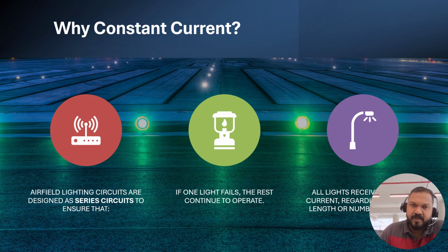From this transformer to the lights placed on the runway center line and the edge lines, similarly the taxiway center line and edge lines. So these are the light placements. They are connected through the duct banks with series type transformers. So this is how the connectivity is happening.